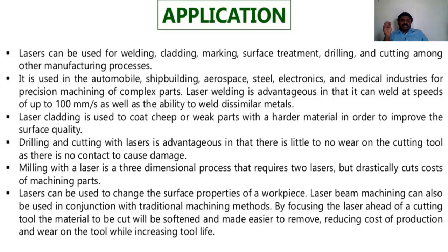Okay, and drilling and cutting with the laser is advantageous here, because it is especially useful for brittle material. There is no wear taking place on the cutting tool, and no contact causes damage. Okay, only the cost is very high. That's the only problem here. Remaining, experience is required, and a skilled operator is required, especially here.